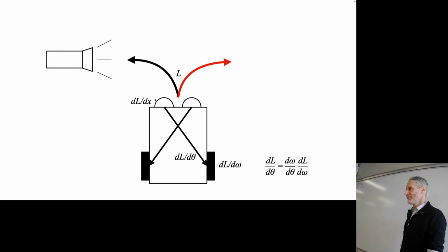Exactly. So let's think about moving x to the left first. If we move x to the left, as you say, the sensor is going to be closer to the light, which means more light is falling on that sensor, which means the signal getting down to the wheel is stronger, which means the wheel spins faster, which means the robot turns more to the left, which means the red arrow tilts a little bit more to the left, and we've reduced L.